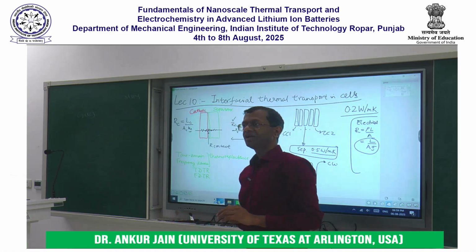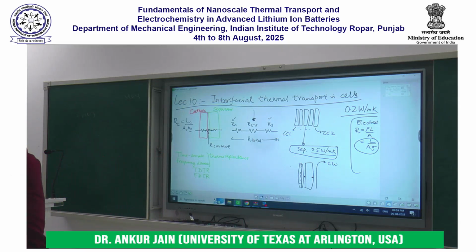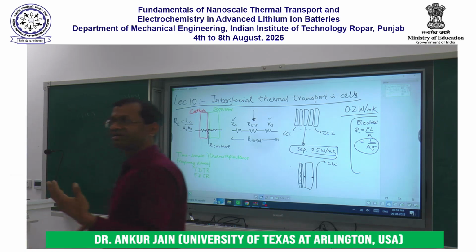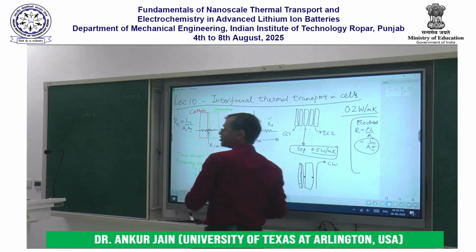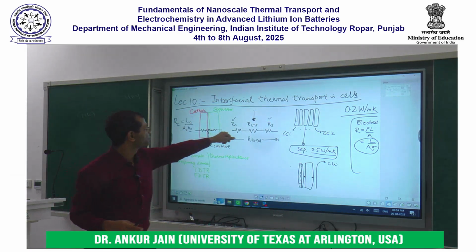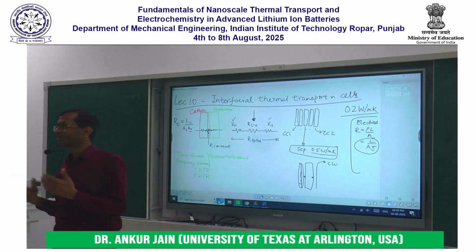Right? And if I know the total thermal resistance and two components of it, I can simply subtract them out to indirectly measure my contact resistance. In other words, if the total measurement turns out to be 100 and these two components are 10 and 40 respectively, then clearly the contact resistance must be 50. Just simple addition and subtraction.